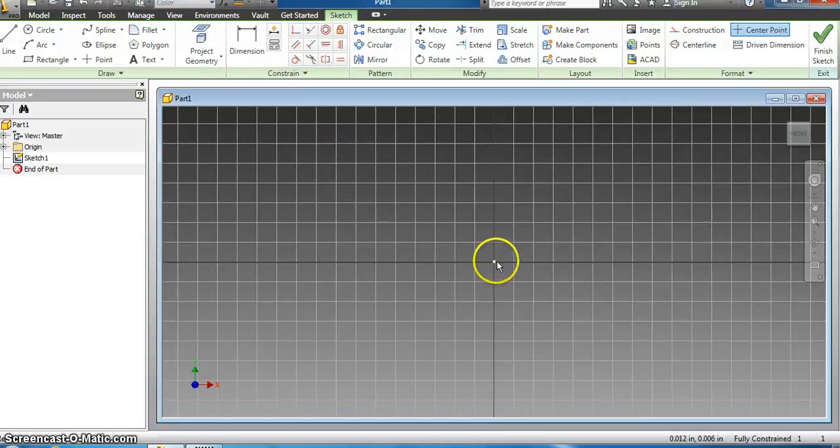Typically what I do is start my drawings here at the origin, which is that center dot right in the middle of your screen. So I'm going to click on the line tool, and I'm going to go over to that dot. You can see how it gives my X, Y at 0, 0. That's the origin of the actual drawing. So typically, that's where I start all my drawings. I'm going to left click, and I'm not going to left click again to end. It created a start point for me at that origin.